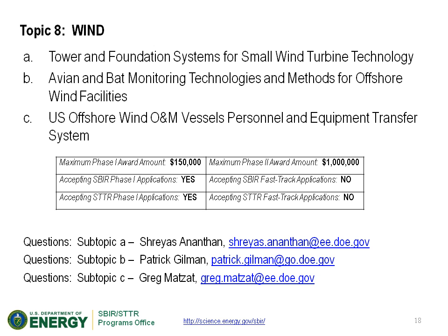So applications are sought for innovative self-supporting monopiles or an alternative technology that can reach at least 35 meters tall, meet OEA and IEC standards which are provided in the topic area language, as well as applications should also include a baseline cost and cost reduction estimates for total life cycle costs. And that's basically saying anything from the production of the towers and the foundations through operations and maintenance and even decommissioning.